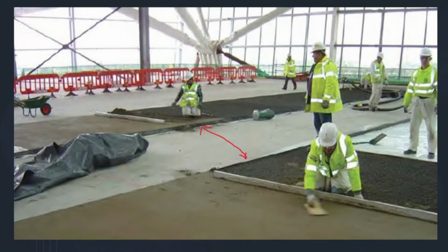You have to lay it in strips of 3 meter or 2 meter width, and length as whatever you can go ahead with, or whatever ready floor you have. Later it can be divided or cut with grooves to make panels of not less than 12 to 14 square meters. So if you are going with 3 meter width, you can go with 4 meter or 5 meter length. Like this, you have to make the panel.